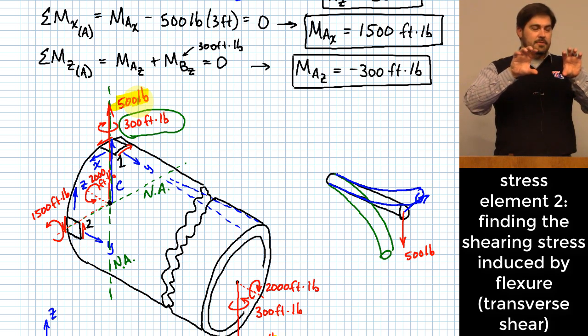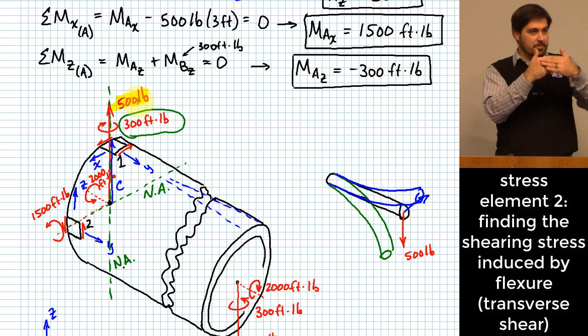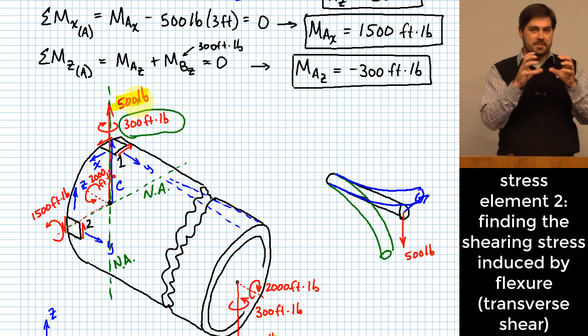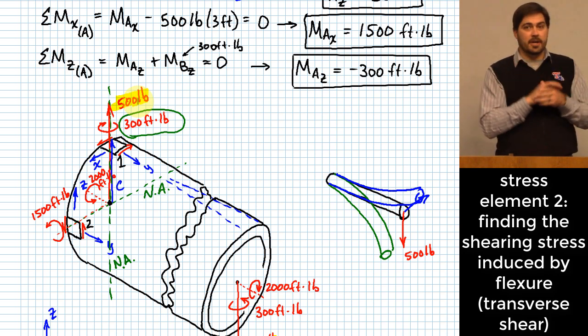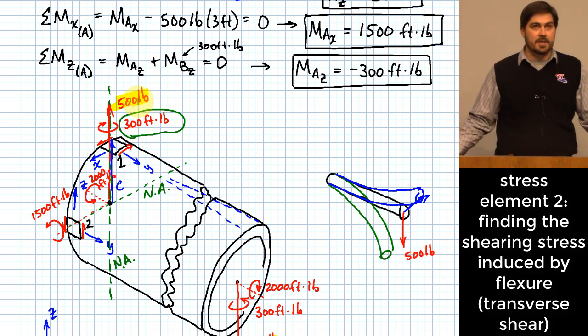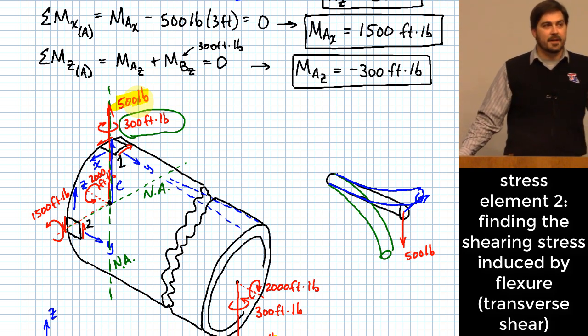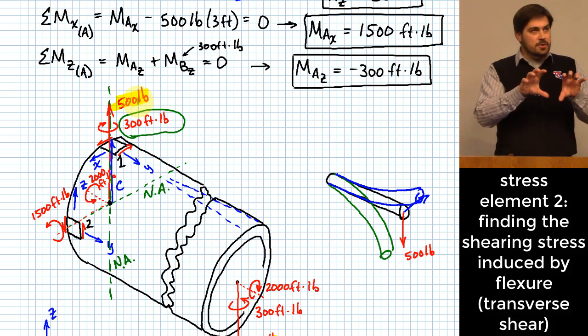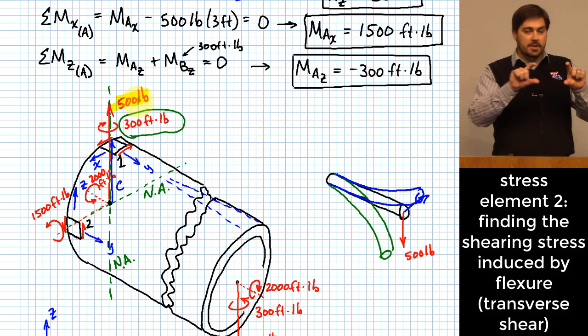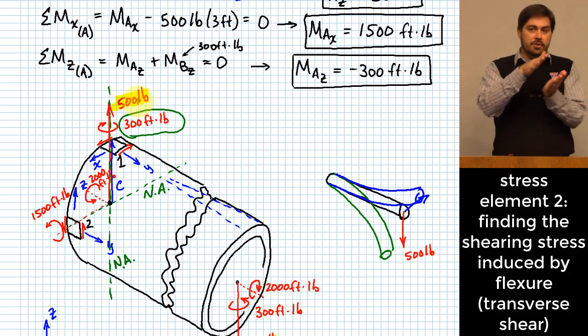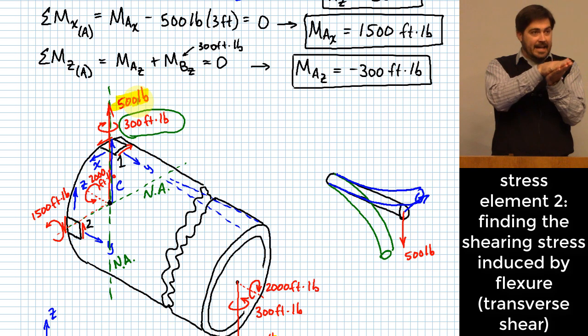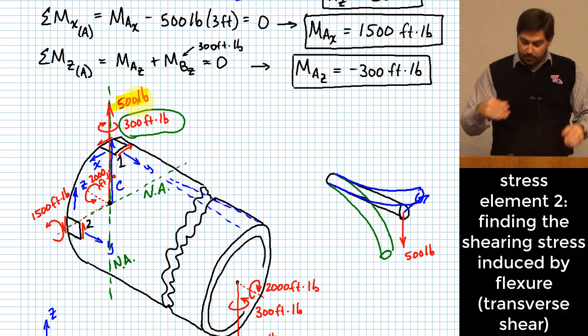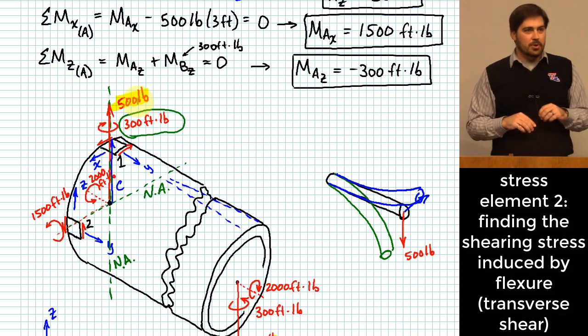And what's the difference? Because you actually have the same material that composes the entire thickness, but it flexes easily in one direction and it doesn't flex in the other direction. So there's got to be some difference there. Yeah, intuitively, the difference is that in the direction where it's bound, it can transfer shearing stress between the layers of pages that compose the phone book, right? And that's the type of shear that we are trying to account for with the idea of transverse shear.